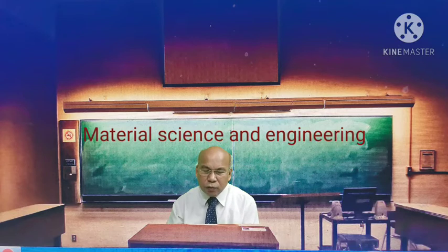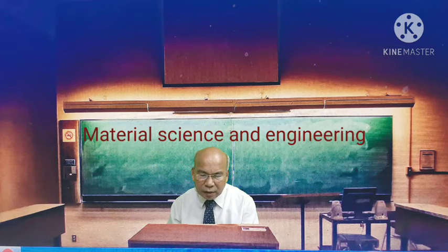If it is heated up to 400 degrees centigrade and then cooled, it's called a medium temperature tempering process. If it's heated up to 200 degrees centigrade and then cooled, it's called a low temperature tempering process. Generally, low temperature tempering processes are performed for cutting tools, measuring tools, and so on. The medium temperature tempering process is performed for springs and coils. And high temperature tempering processes are mainly performed for high carbon steels.